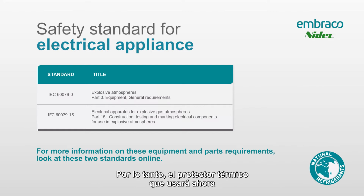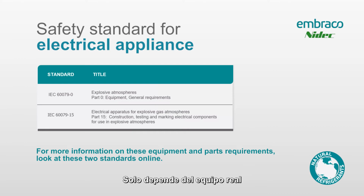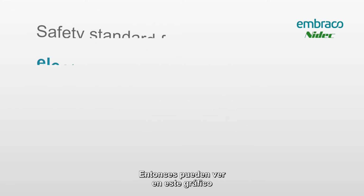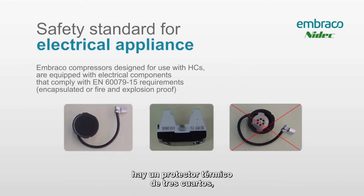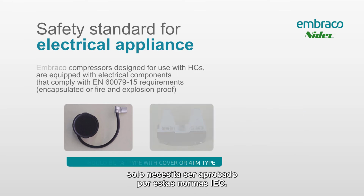So the overload protector that you'll be using now may look a bit different than it did in the past. It just depends on the actual piece of equipment and where that piece of equipment is inside the cabinet. So you can see on this chart the difference that I'm talking about. On the right hand side is a 3/4 round or clicks-on overload, and that's one that will be used on our R134 or 404 compressors. On the left hand side is what a new one's going to look like. So everything that is potentially spark producing is now enclosed. In the middle we have a 4TM type overload protector, and it was already inherently safe. Just needed to be approved per these IEC standards.